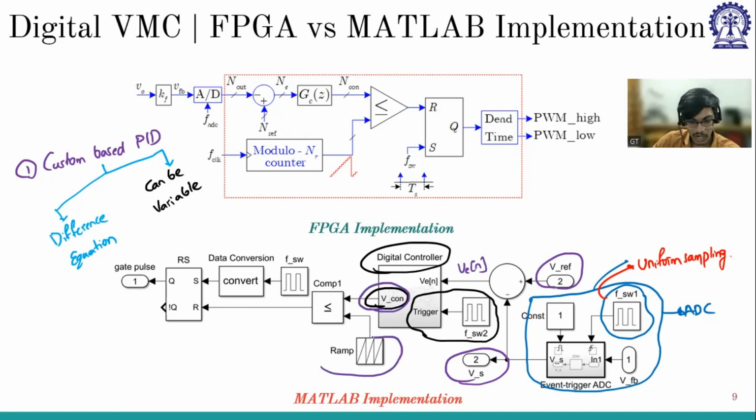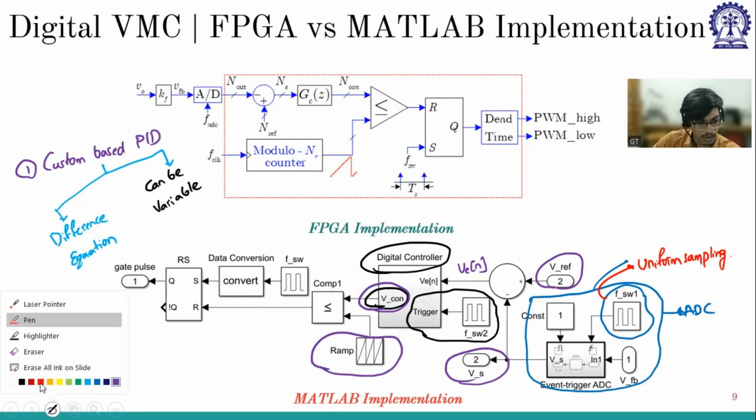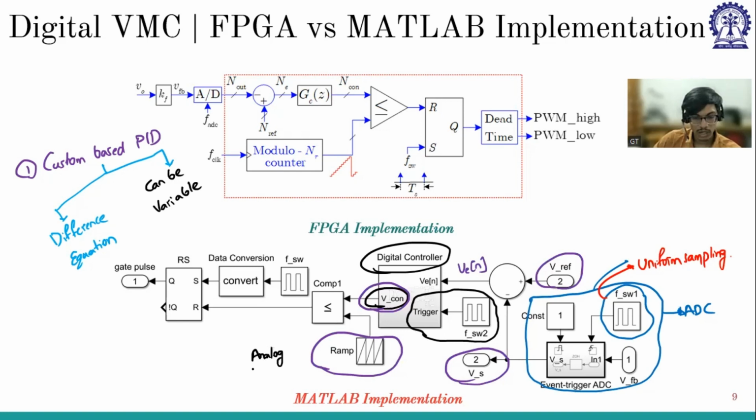And the ramp here we have considered is a smooth analog ramp. This is an analog ramp, not a counter, not counter based DPWM. For ease it was considered, but you are free to use a counter also. Because this is a ready-made block, we had used it. Again, for counter based, you have to use another block and see how to work with that block, and then comparing it gives the reset pulse.